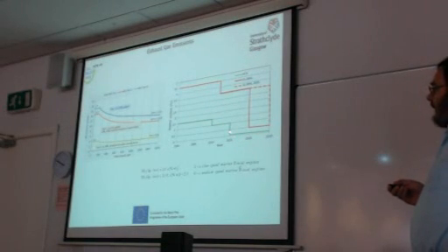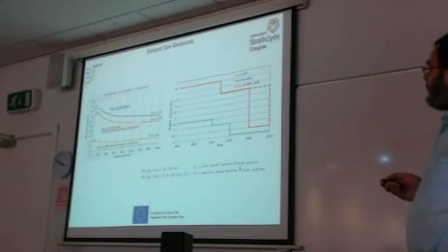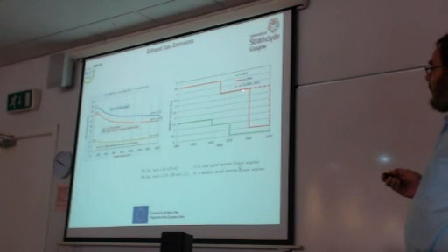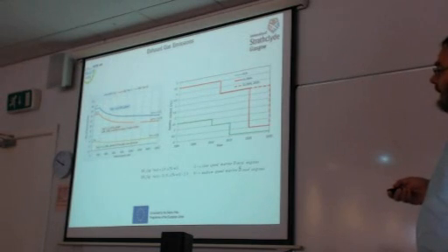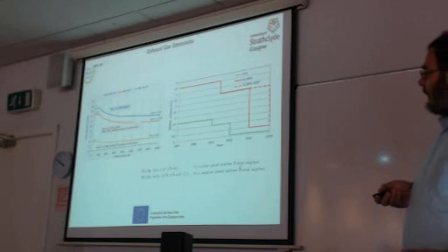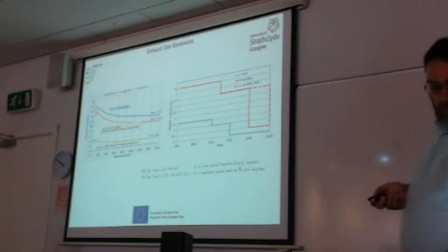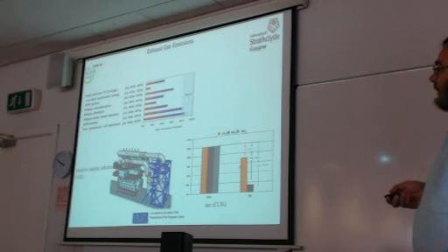So also we need to know that there are two areas. There are emission control areas called ECAs, where the permitted sulfur content is very low, 0.1% from 2015 onwards. And in the other areas, up to now, the permitted sulfur content is 3.5%, but there will be a huge reduction to 0.5% from 2020. So these two factors, emission limits for NOx and SOx emissions, increase the pressure towards alternative fuels or fuels with low sulfur content and fuels that can reduce emissions. And one of the ways that can reduce emissions is by introducing a dual fuel engine.